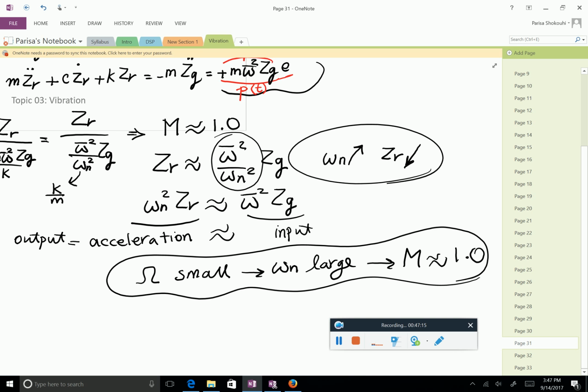What I'm giving to you is the specification of the accelerometer. What you see here is nothing else but a zoom-in version of the curve that I showed you. So you see how m is changing for different frequency. On the other side, you see both phase and amplitude over the larger frequency bandwidth. Make sure you understand this, because in your next homework, I ask you to design a displacement sensor. So use your knowledge to design a sensor which can measure displacement.